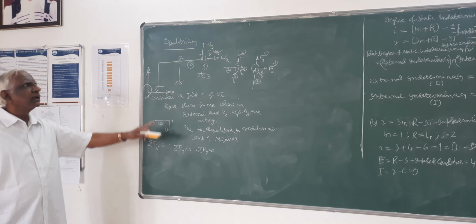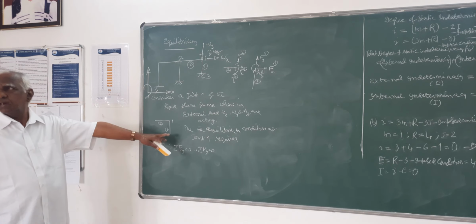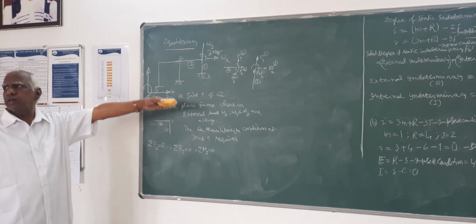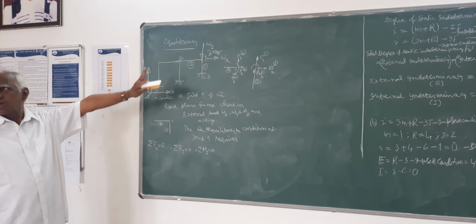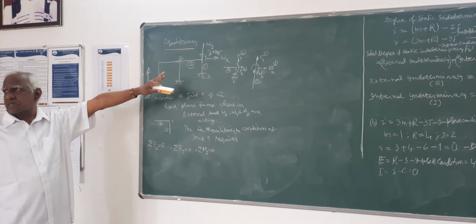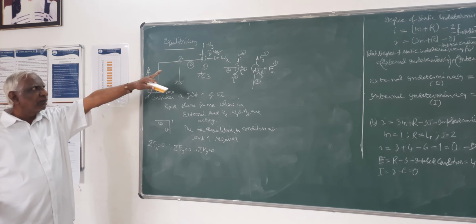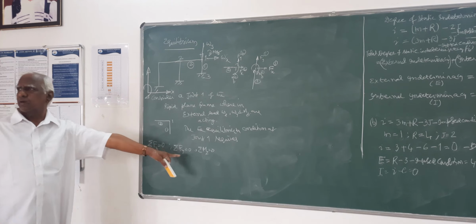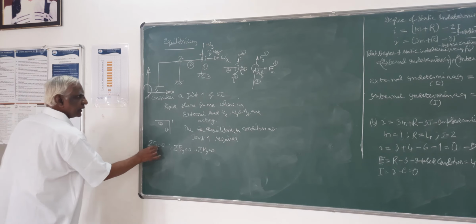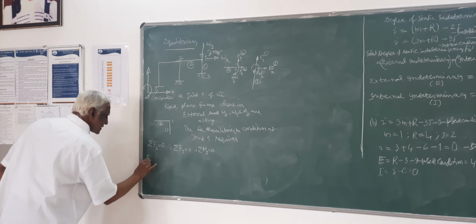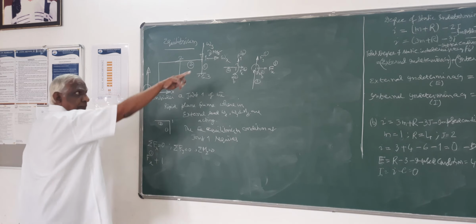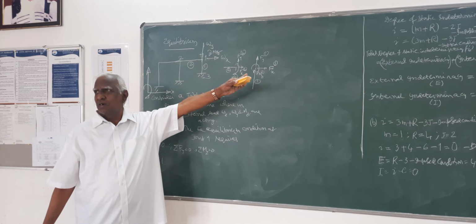So here the equilibrium condition requires that the algebraic sum of all internal forces and all external forces at the joint being considered should be 0. So sigma Fx equal to 0 means this Fx of the first element, which I have taken in the positive direction to start with.